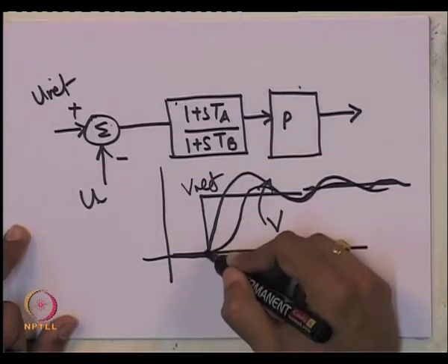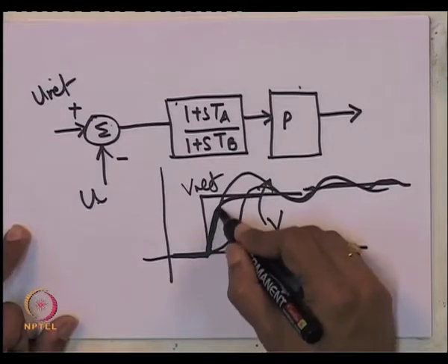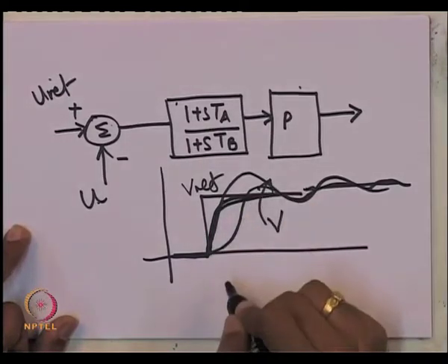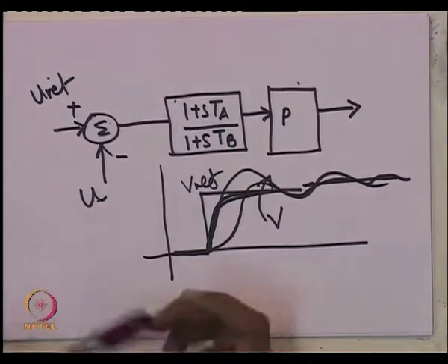The best possible response could be something like this, you want it to rise and settle down immediately. So, that kind of response you could want. In the case of an excitation system, remember that the conditions of the synchronous generator, whether it is open circuited on no load or it is at half load or at full load, will really change the kind of response you will get.